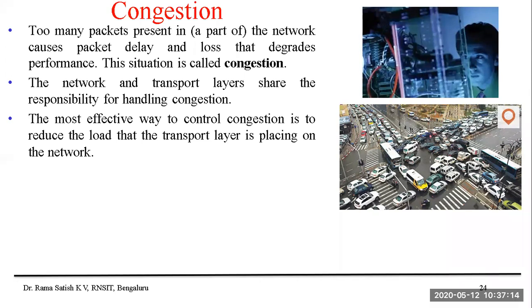Yes. So how to reduce the load? One very important thing is to create more parallel routes. If there is only one route, definitely there will be congestion. Instead, you have an underpass, you have a flyover, you have other parallel roads. So automatically the traffic will be moving parallelly in all the paths, and you can certainly avoid that kind of congestion.